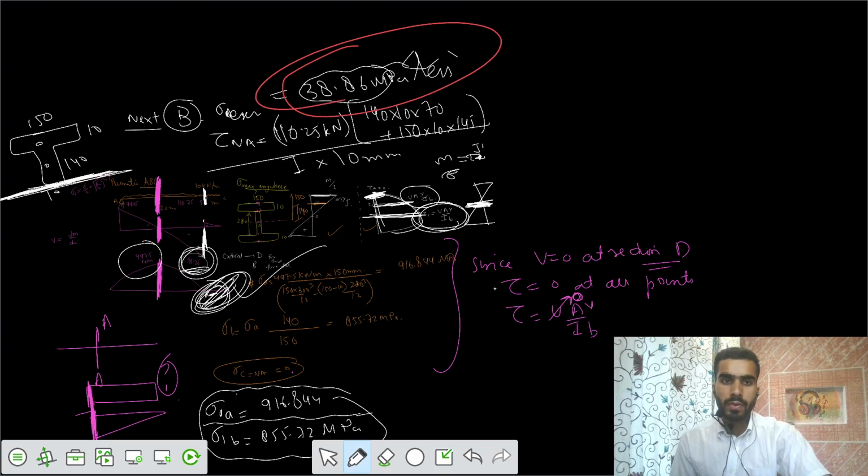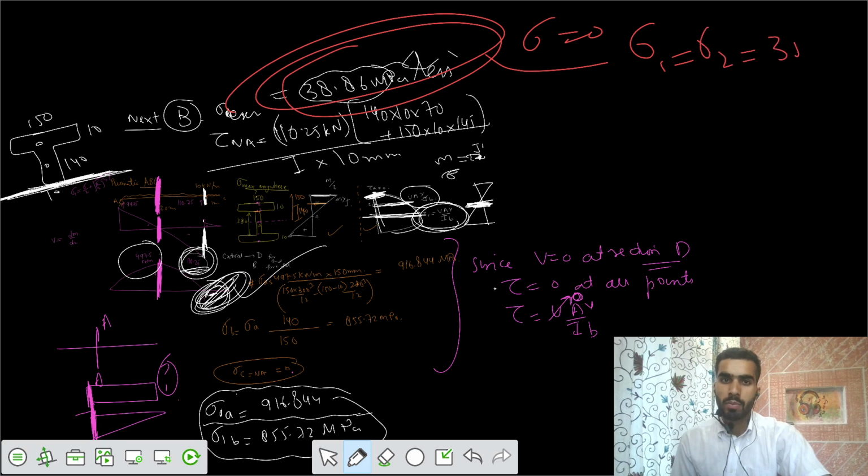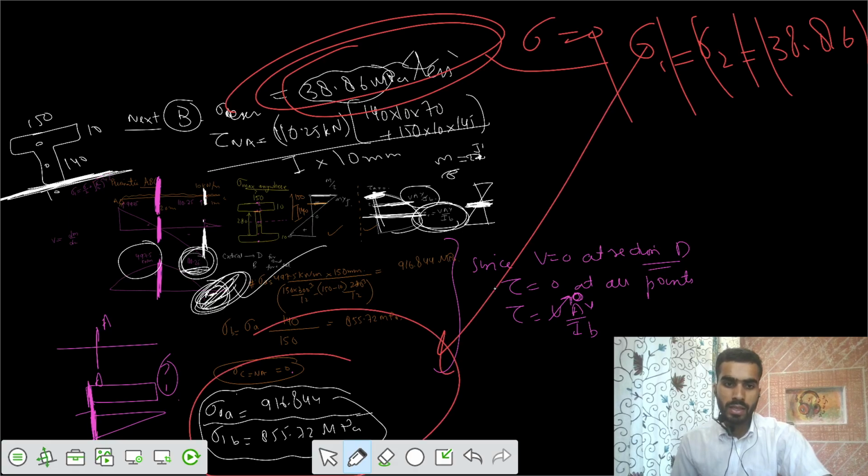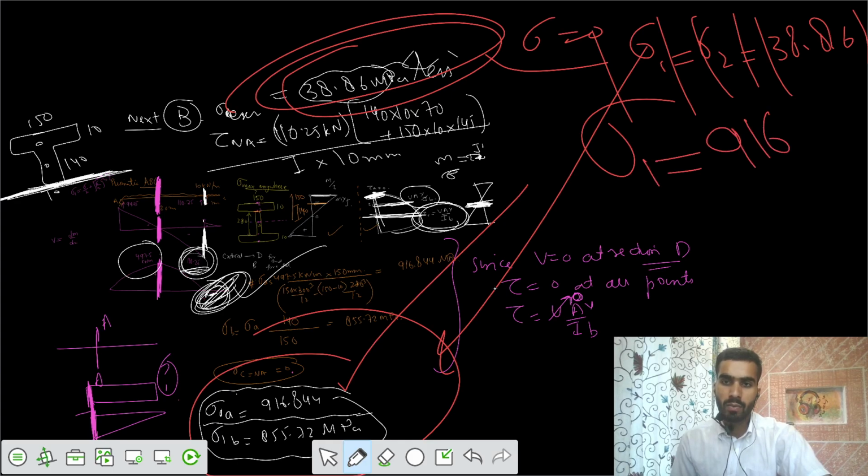Because the normal stress is 0, your major principal stress equals the minor principal stress, which is 38.86. That's very small compared to 916. So your maximum major principal stress anywhere in the beam is 916.844 megapascal.